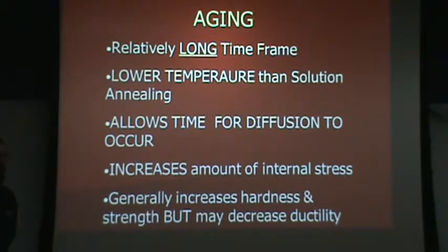When I do that, I increase the strain on the matrix, which increases the hardness and resulting tensile and yield strength. There are a few stainless steel alloys that are handled in this way, and they're commonly used in aerospace applications and others where you need relatively high strength stainless properties.